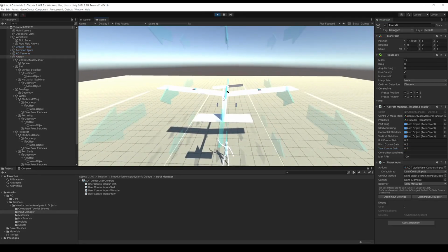So we're from behind, it's probably the easiest place to look at it. So I'm going to do left arrow. So there's more lift on the right hand side than the left, so the aircraft is going to bank with the right hand wing, or the starboard wing, going up, so that's right. And if I play the right arrow, the opposite thing happens.